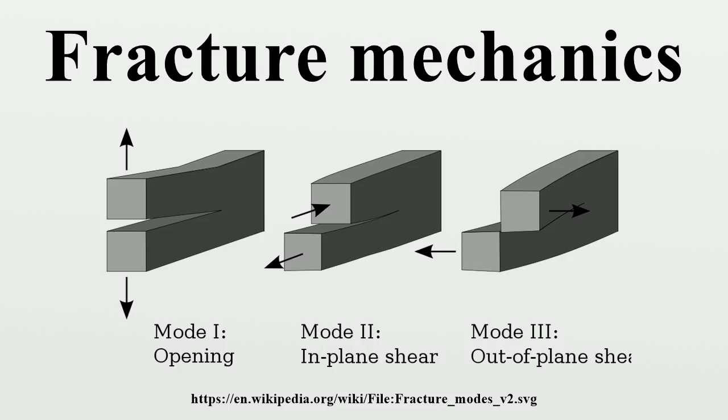Griffith found an expression for the constant C in terms of the surface energy of the crack by solving the elasticity problem of a finite crack in an elastic plate. Briefly, the approach was: compute the potential energy stored in a perfect specimen under a uniaxial tensile load, fix the boundary so that the applied load does no work, and then introduce a crack into the specimen. The crack relaxes the stress and hence reduces the elastic energy near the crack faces. On the other hand, the crack increases the total surface energy of the specimen.